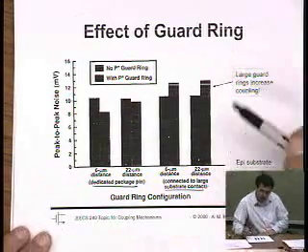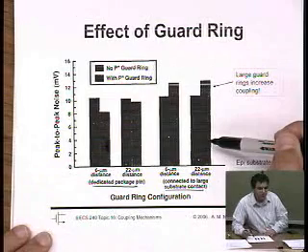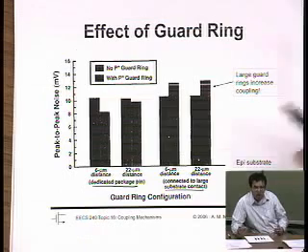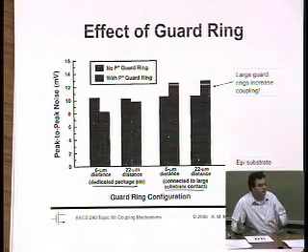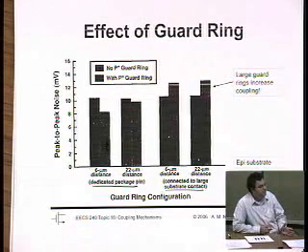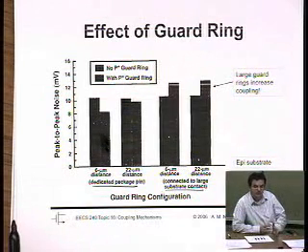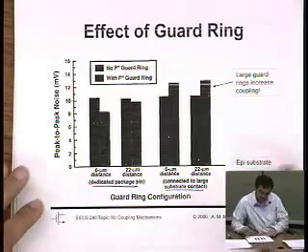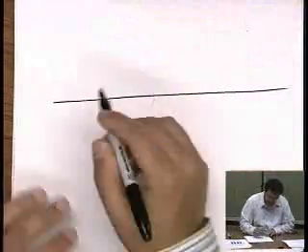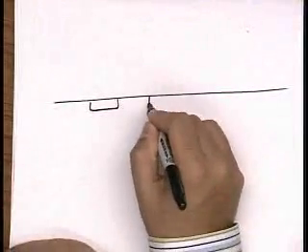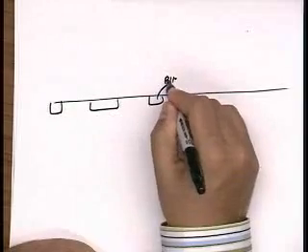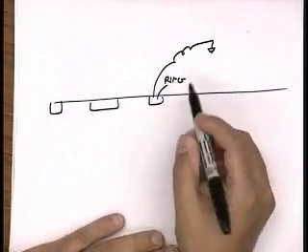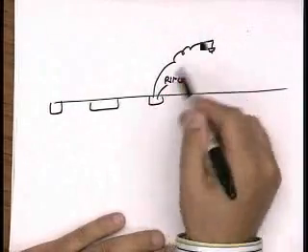Well, it could be one of several things, but remember from last lecture, ground is kind of a dirty place as well. Ground has bond wire inductance, and there's probably more current flowing to ground than current flowing into your dedicated guard ring ground. So the L dI/dt's are larger on the ground than they are on your separate ground. So let me draw a picture. Again, I have my sensitive node, I put a ring around it, and let's say I tie it to separate ground. Then this is a pretty quiet node. Not much current is flowing through here.